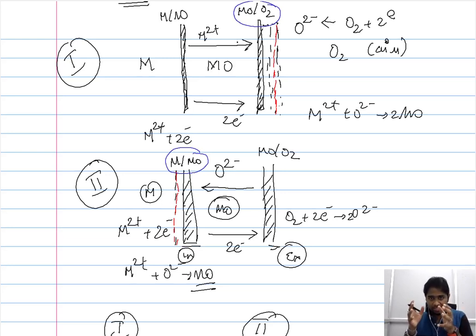Even though the thickness of the metal oxide remains the same, it doesn't mean that the consumption of the metal has stopped. This is because when you have the formation of new layers on the external interface, because of the nature of the new layers being formed, it is possible that in certain environments they get removed. So even though the metal oxide size might remain the same, the consumption of the metal continues.